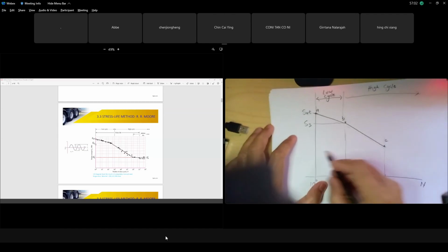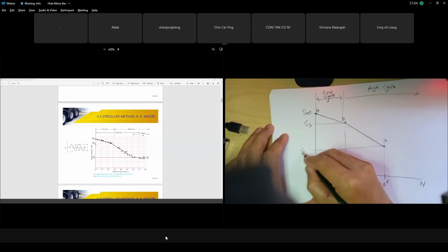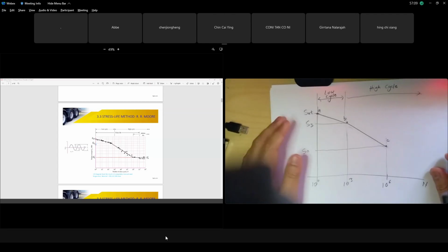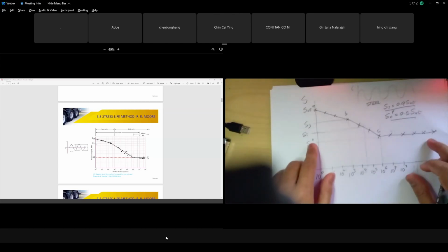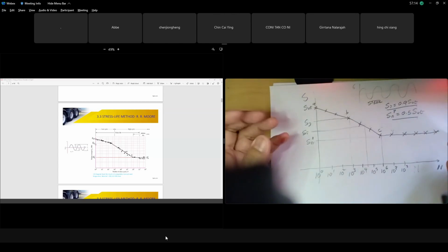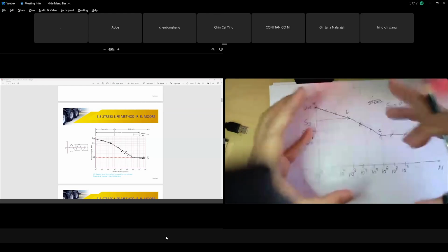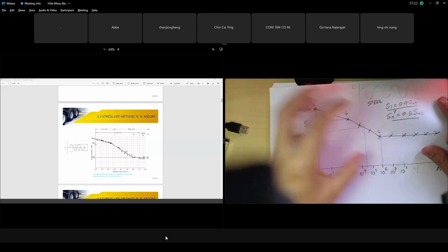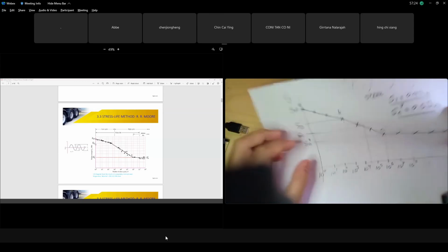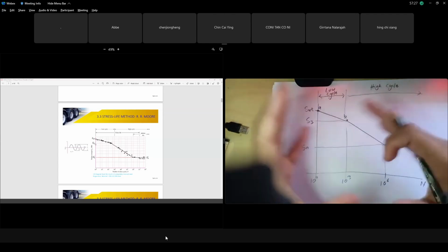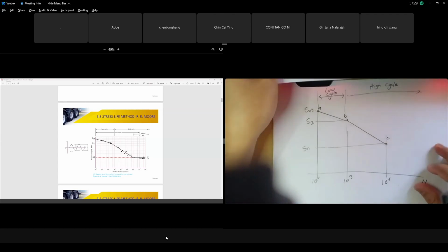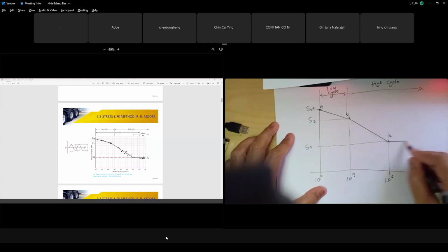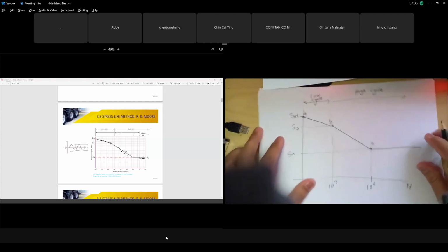This is your SN value, guys, your SN graph. But if we compare with the RR Moore test, it is SN prime, because we have the modification factors CL, CG, CS, CTR. This is a standard test done by engineers on a standard test specimen, so we have to use modification factors to adjust. That's why we have our graph like this. The plot is still the same, but the values are multiplied by the modification factors. After 10 to the power 6 it becomes a straight line. This is the high cycle region.